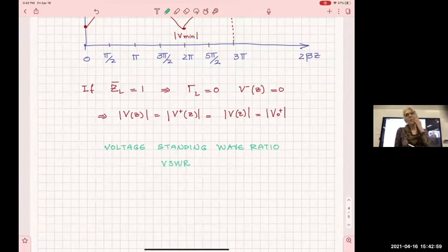So if I go, for example, to purchase a component from a vendor, let's assume it's a low noise amplifier or a filter, I'm going to put it in my circuit. They will tell you how much the VSWR is going to be at the input port. They will tell you that when the output port is matched, the input port is going to give you something. And this VSWR is going to give you a good idea of how far off your design is from the optimal.